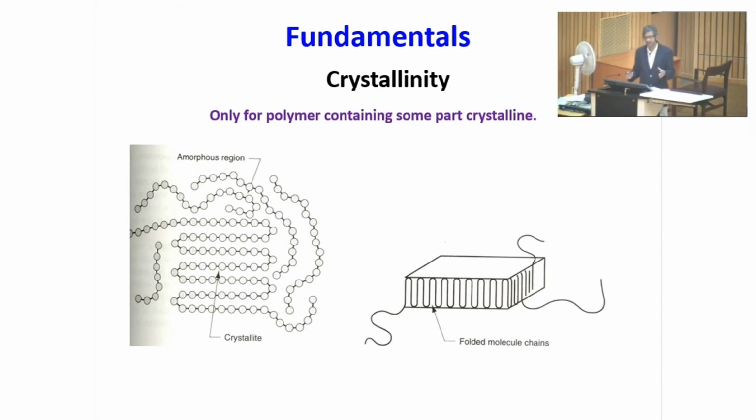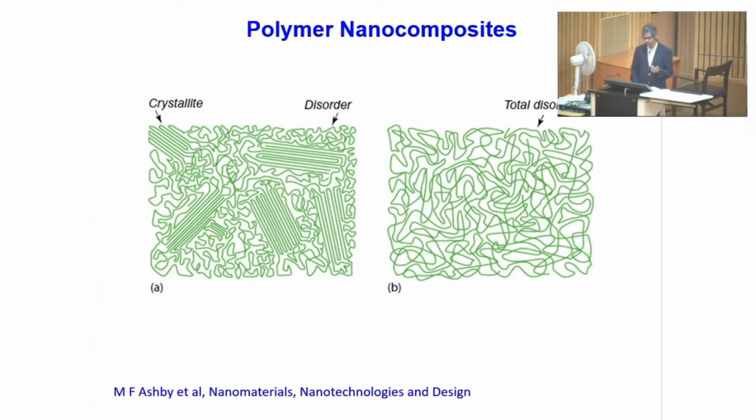So, what is the meaning of this? You can have a bit of crystallinity in the polymers, and this actually affects the properties of the polymers extensively. When you add nanomaterials like metallic, ceramics or carbon based into the polymers, these kinds of things can happen. The amorphous polymer can get crystallized in some part of it as a crystalline polymer.